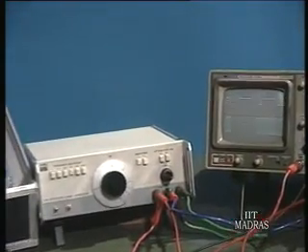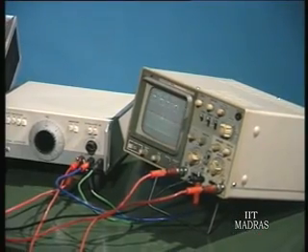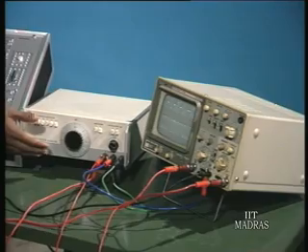One input corresponds to a modulating frequency of 100 hertz. Another corresponds to the carrier, which can be varied, of course, but is kept at about 1 kilohertz. You can see the lower one corresponds to the carrier, and the upper one is the output of the multiplier. Since these frequencies are not very stable, it can be triggering only one waveform properly. We see that kind of movement there, and it is